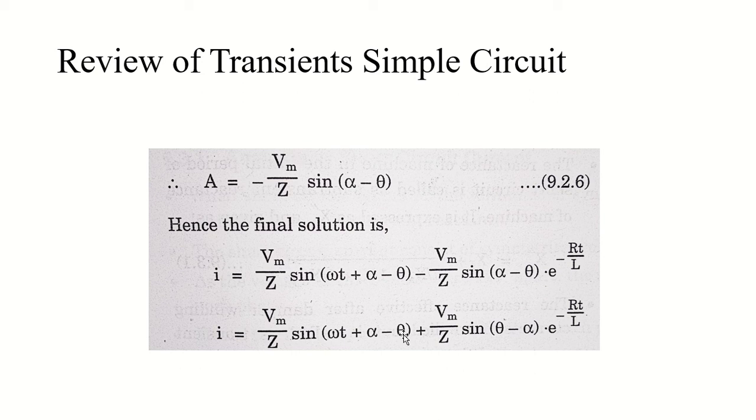The second component is the transient component, and this is that little nasty component which will be causing trouble all the time. That transient current is also known as the DC offset current. It will decay exponentially with the time constant L by R, because of this term, right? It decays because of the minus R by L given here, and exponentially because we have an exponential function here.